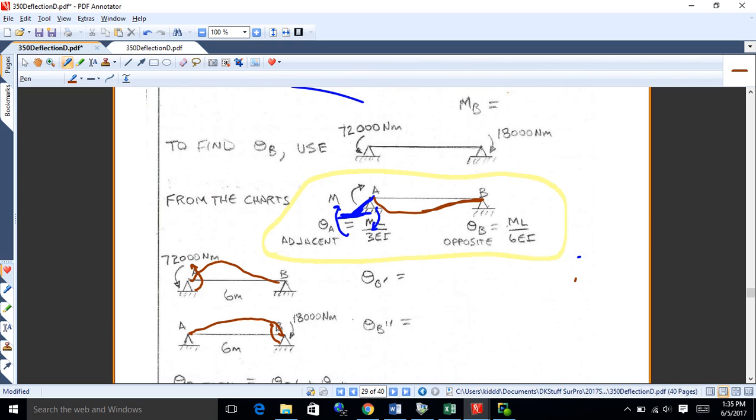Getting something like that, they both bow up, concave down, the both of them. The other way to tell is just kind of extend the same direction on the opposite side of the support. That kind of tells you whether the couple is pushing the beam up or not. Here in both cases, if I continue the counterclockwise one on the top, it'll just come around counterclockwise. That'll push that side of the beam up. And the clockwise one on the right will push it up also as it continues around clockwise. So that might be another way to look at it, rather than that T-bar.